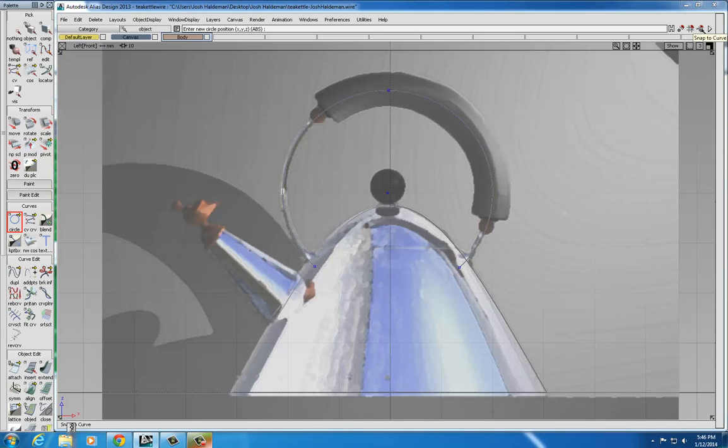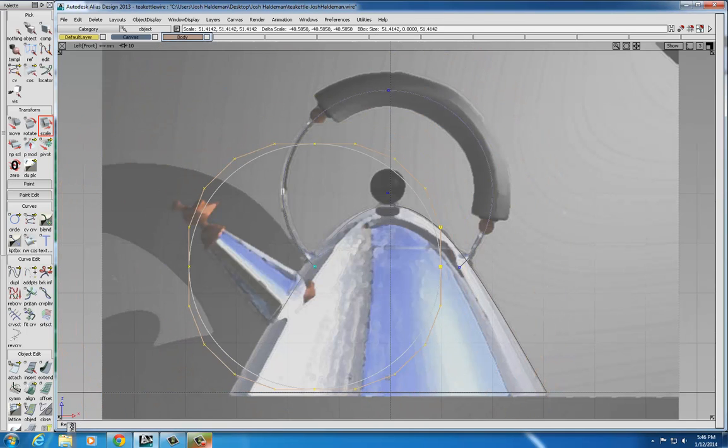Snap to curve using the snap tool that's in the upper right-hand corner. And then I'm going to click on that 3-point arc that I just created and modified, and I'm going to drag that circle down to the start point of the arc on the left-hand side. Now you'll notice when you initially place it, the circle comes in too big. We need to scale it down first. So if you want to scale it manually, you can. Choose the scale tool and just click anywhere on the screen outside of objects and hold with your left mouse button and drag to the left.